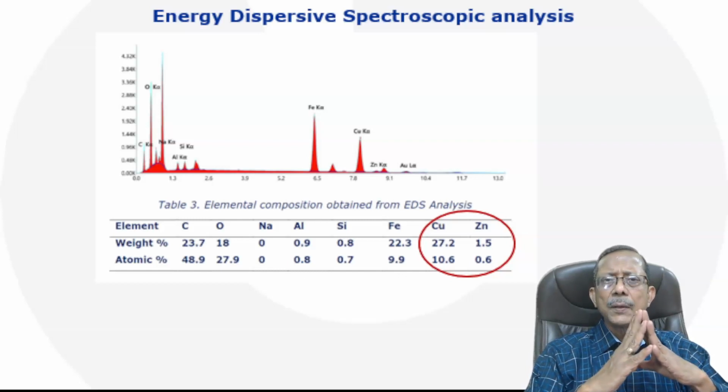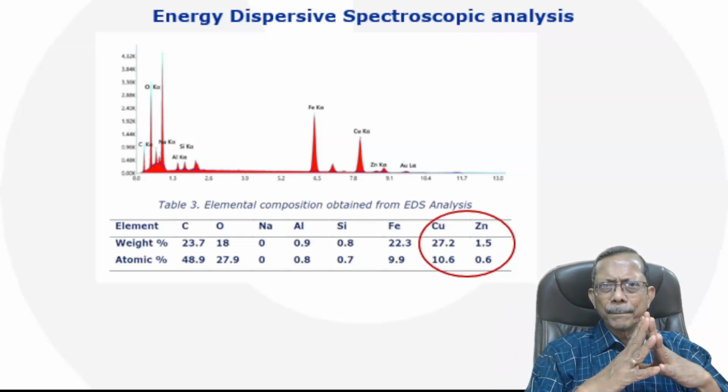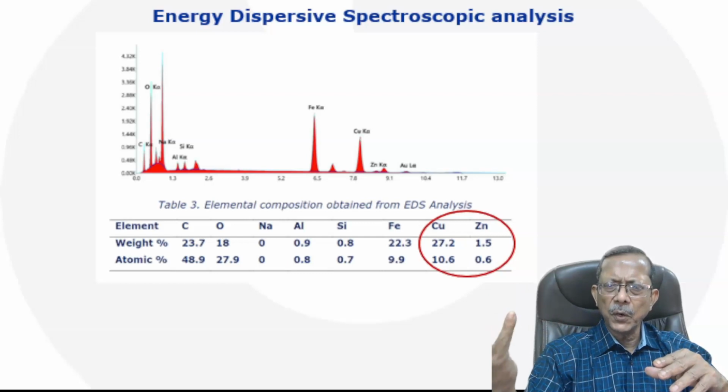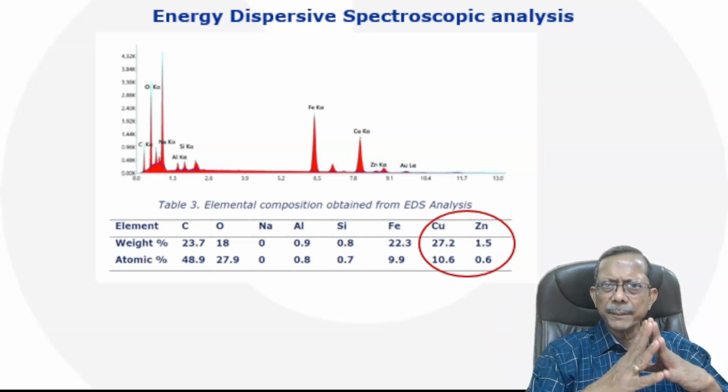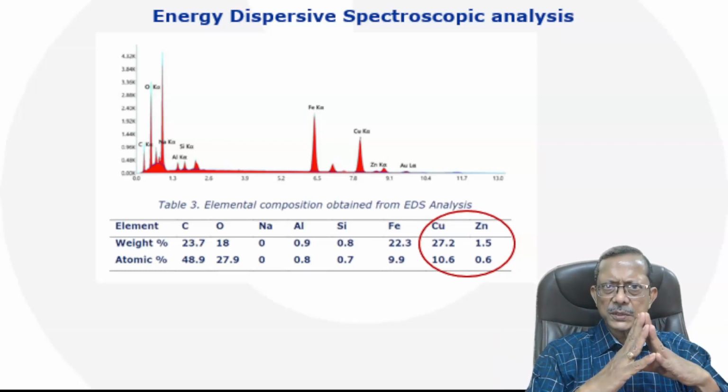But the question is, from where are the copper and zinc coming? Usually in a power plant boiler condenser, you get admiralty brass metallurgy. Admiralty brass is nothing but copper and zinc. But when I talked to them, they said that their CPP boiler condenser, that is the turbine condenser, has stainless steel metallurgy. So from where are the copper and zinc coming? That is the first question.